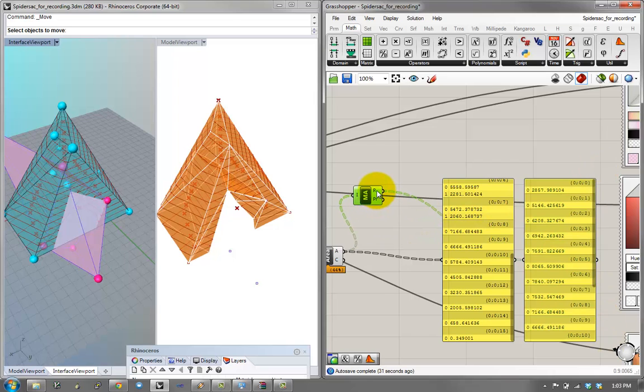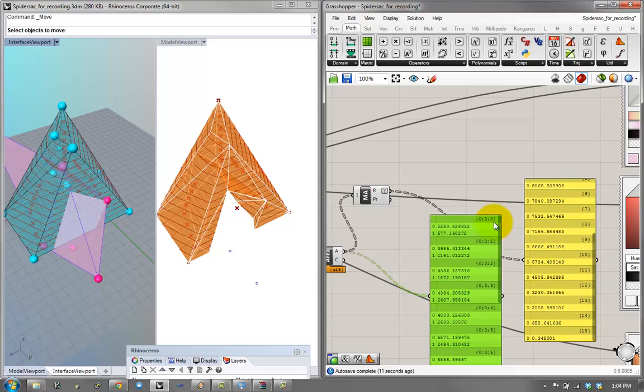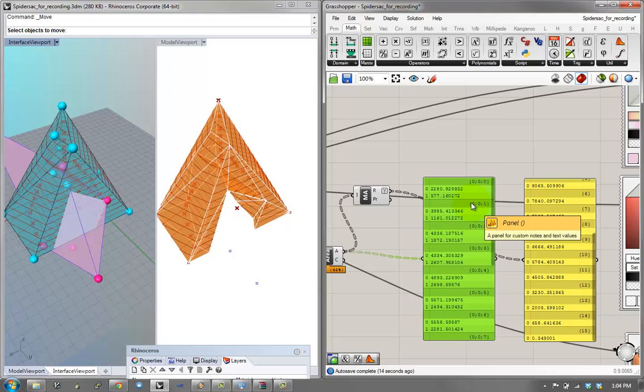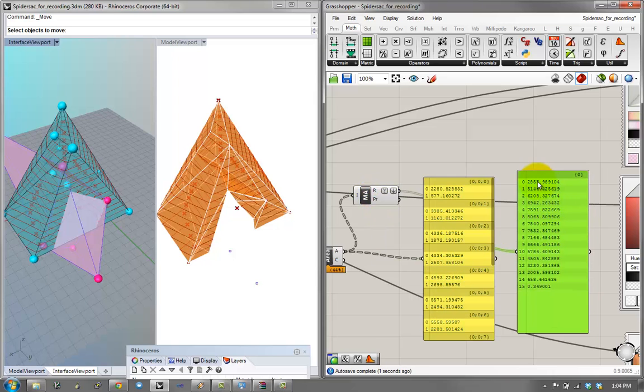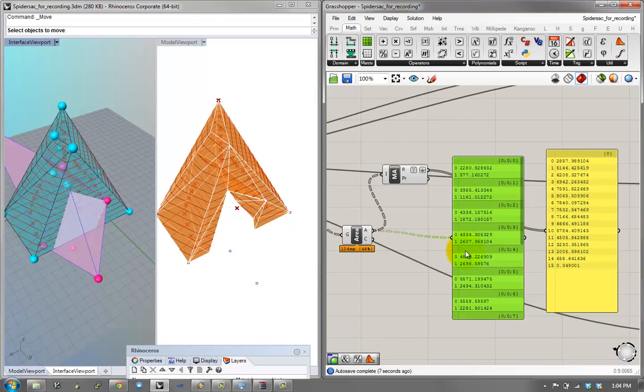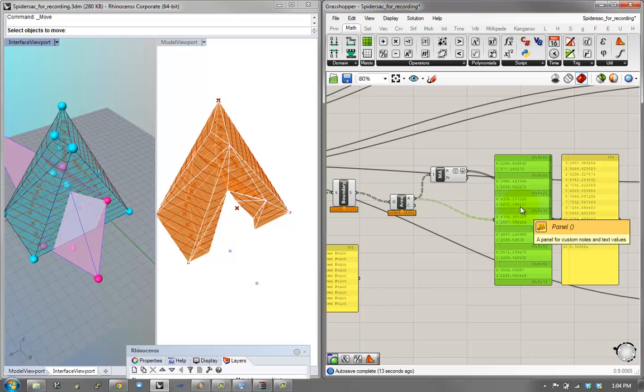And that's this one. And again, I'm going to right click and simplify and make this into a simple list. What I've done is remove any redundant information. Again, this is a tree operation, and you should look at the tree video if you want to gain a lot more information about what this just was. But this basically makes it a vastly more simplified list, and I can actually use the flatten function to make it into an even simpler list. Again, you should really look at the tree video. It'd be a lot of great help to understand exactly what I did, especially since trees are kind of at the core of Grasshopper.